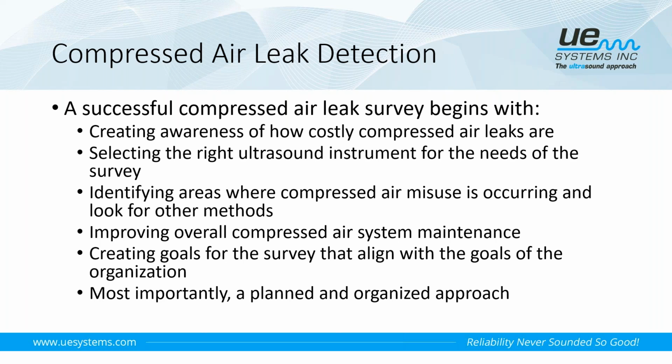Again, through these teams that can go out, such as an energy treasure hunt, we can identify areas where we have excessive misuse of compressed air, and we can potentially look for other methods to do the same task without using compressed air. Again, we think about making massive improvements to the overall compressed air system. Once you've gone out and located and repaired leaks, then we can think about doing some of those types of capital investments. We would want to create goals for the survey that align with the goals of the organization.